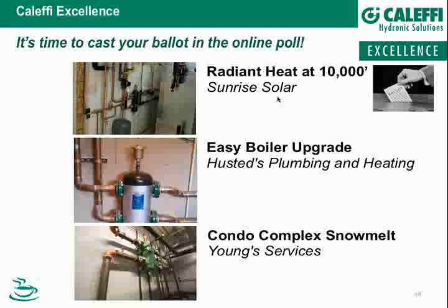For example, if you were to study the close coupling arrangement and then take the two pumps and separate them by maybe 12 pipe diameters and see if there's any suppression of turbulence coming off the upstream pump that would have a beneficial effect on the performance of the downstream pump. I don't know that to be the case, but generally I think if the two pumps are going to be close together, usually they're going to be close coupled.